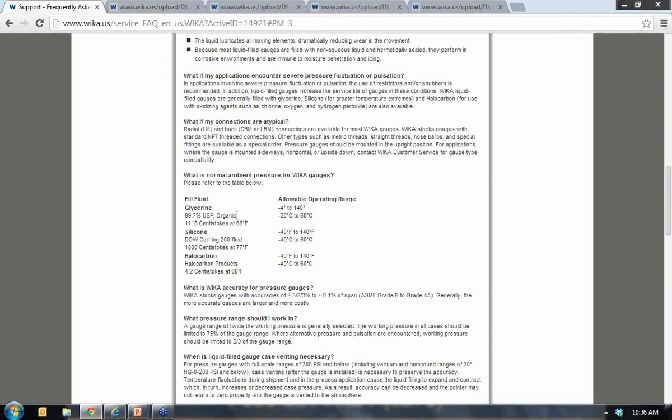Yeah, no, I agree with your answer. I think the best way to do it would be to put a diaphragm seal in and separate that moisture out. Keep it in the process.